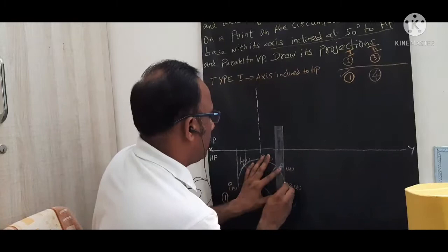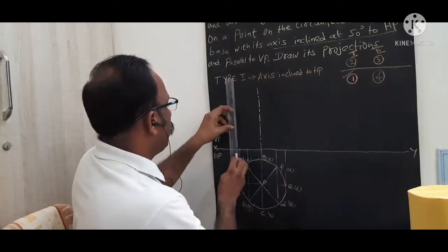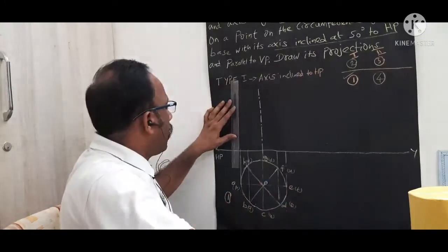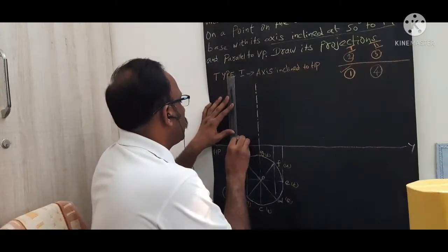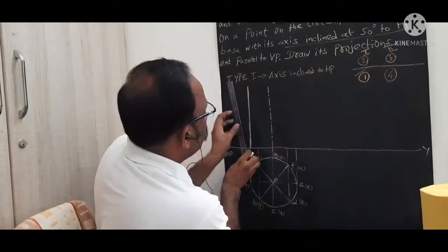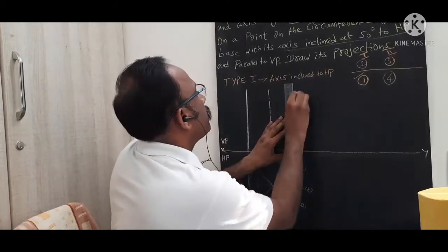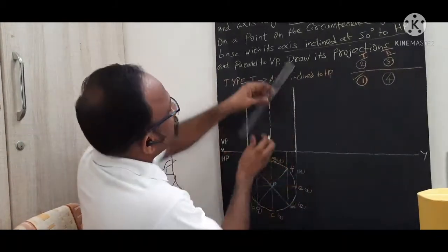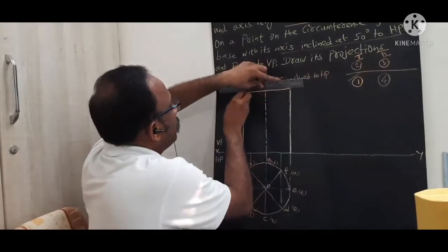That's the way we are going to solve this particular front view. Now I am going to draw this outer line, because the front view we can see only as the rectangle. So outer edge only we need to draw the thicker line for the 70 mm height.